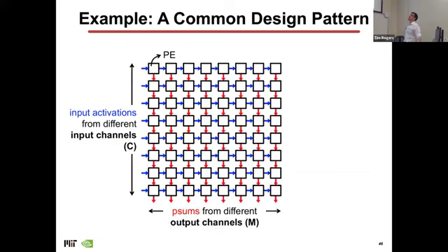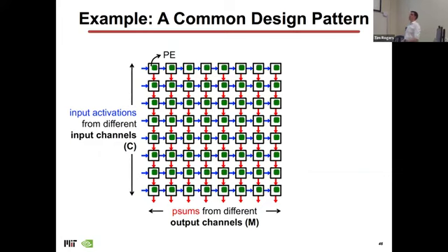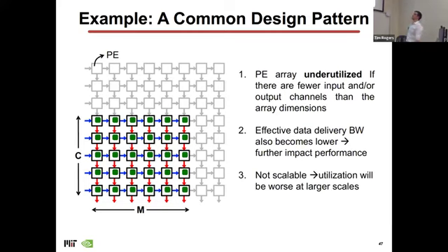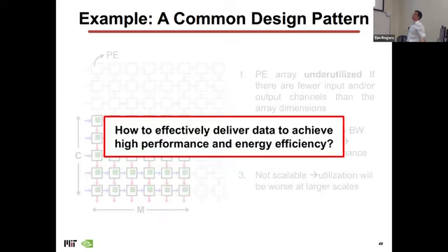All right, so here's an example of how they do this, right? They have a bunch of input activations that are flowing in. This is a common configuration. This is going to be weight stationary. So showing this for weight stationary, coming downwards across the row like we've seen. And then, of course, when you try to map the actual layer, you can't use all of the processing elements. So only a subset of them are going to be used. So that decreases the maximum potential.